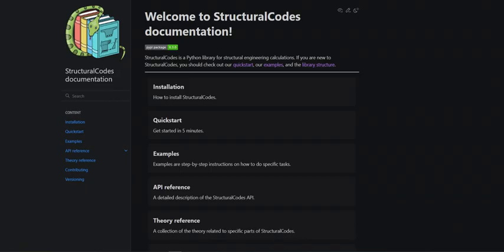In the next block, we create geometry objects. In structural codes, the geometry objects contain both a polygon and the material that's related to this polygon, or a point and the material related to the point. So we define a width, a height, and we construct a polygon. So this will be our rectangle for the rectangular cross-section. And we're creating a surface geometry. So here you see that we refer to the concrete object again. So geometry here, that's the polygon with some material assigned to it.